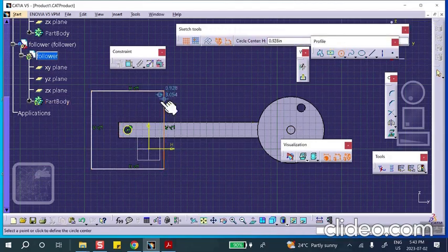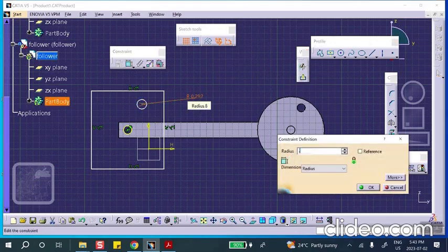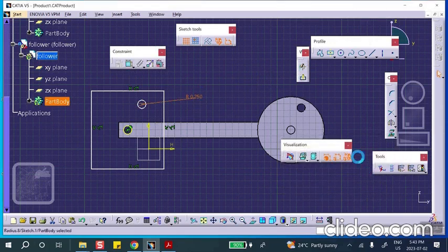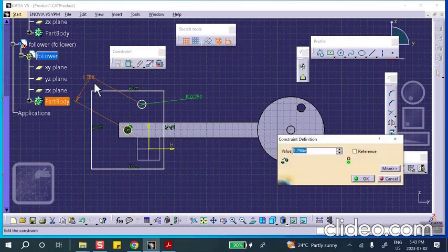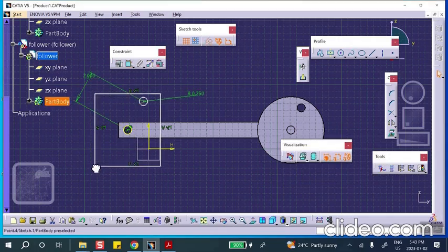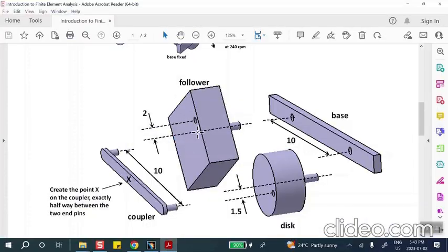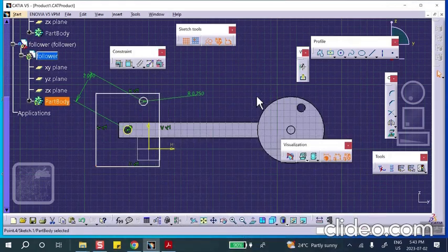I may have to change the size of this because I need a hole here which is 2 inches away. So let me put the hole there, 0.25, right? 0.25. I'm making all these holes 0.25 to make my job easier. And then the distance between the center of this hole to the center of this to be 2. Okay, that looks good. If you want to make these things bigger or smaller, that's entirely up to you, but it really doesn't matter. The only thing that's important here is that the distance from the center to the center of rotation should be 2 inches. Okay, exit.